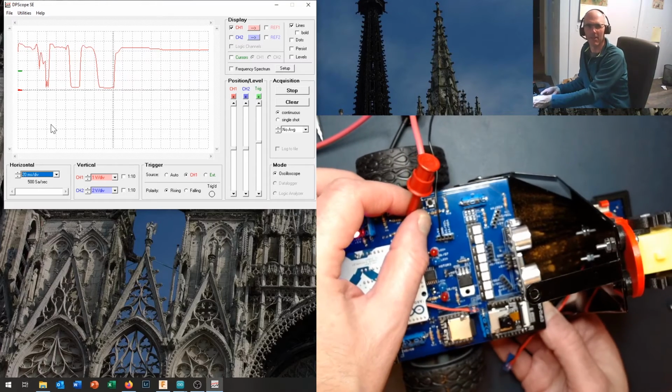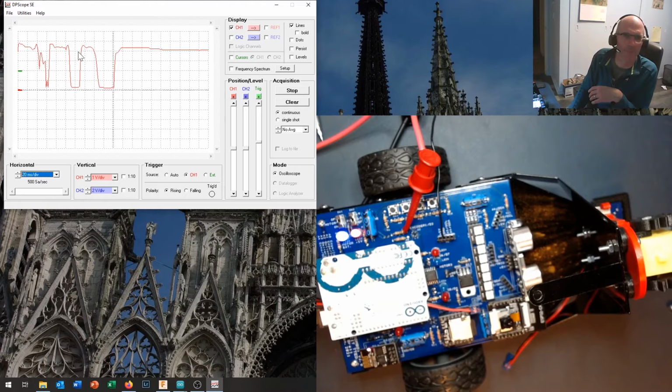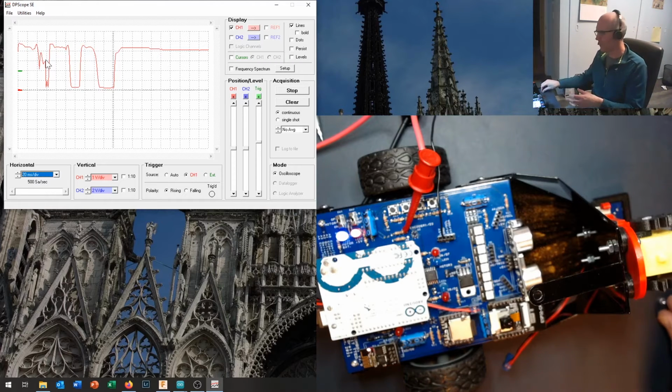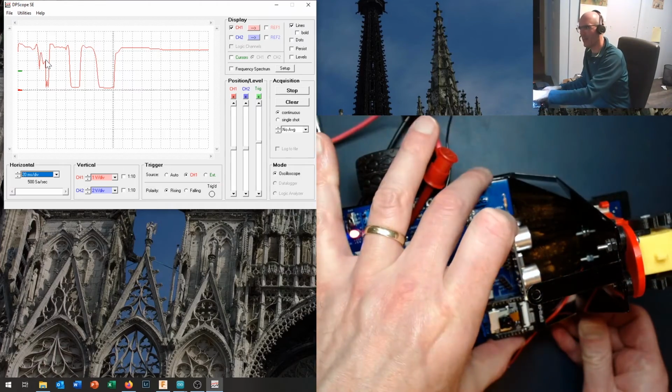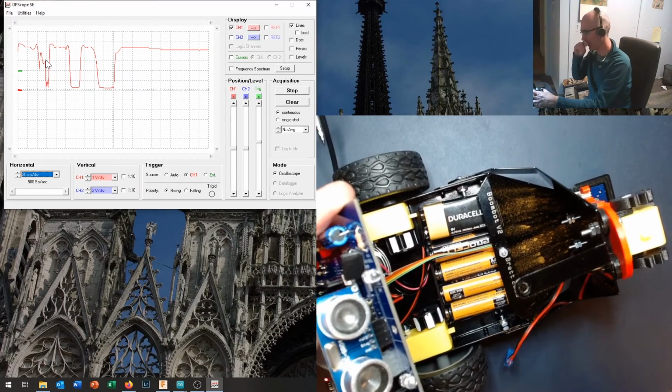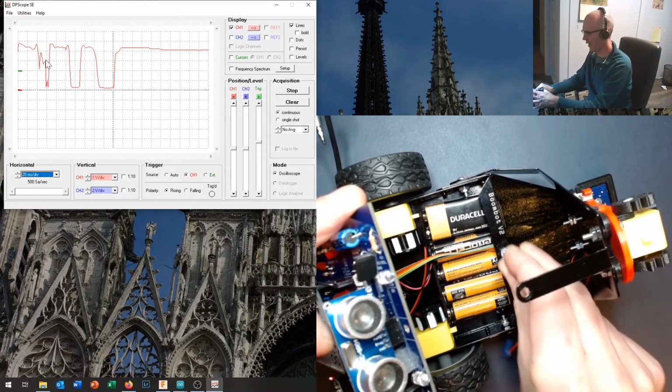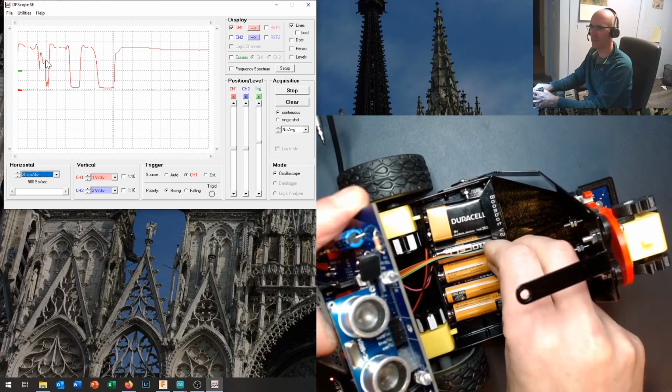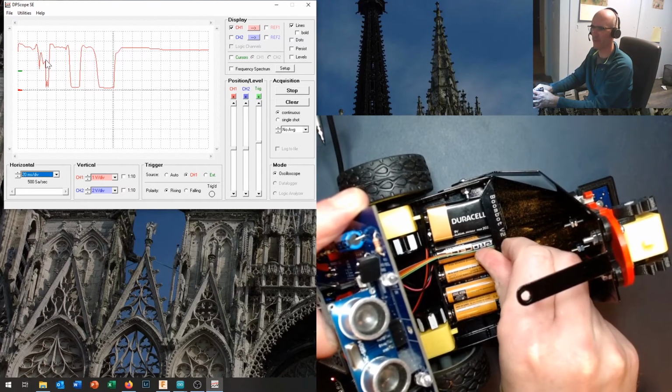And now the peaks are a little further apart, but you can tell a couple things in here. They're all taking roughly the same time, but look at some of the noise and gunk that I'm getting in right here. Now, I don't have a great explanation for what exactly is causing that noise and gunk. Maybe I didn't fill in the white quite as white on one of the sections. Maybe the 3D printer is more reflective than I thought it would be. But what I have found is that if I get the height of that sensor off of the encoder ring absolutely perfect, I don't get those flaws. And so on my robot, the trick is to add a third 440 nut on there.